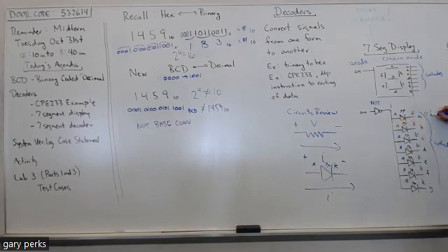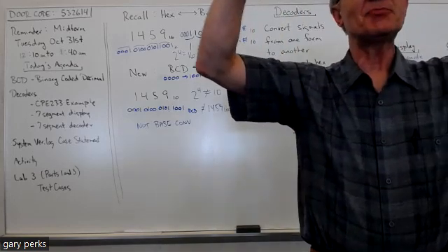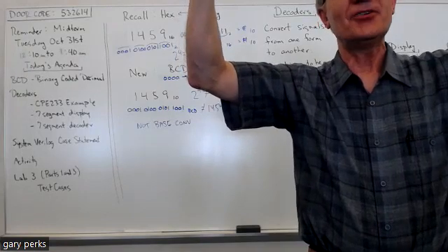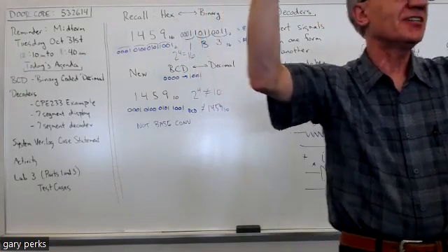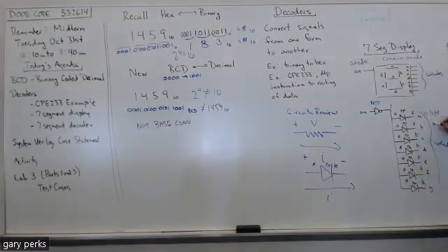So if you put a 0 on the cathode of the segment, that segment will light. If you put a 1, well, now you've got equal voltage on both sides, right? You'd have 5 volts on the anode and 5 volts on the cathode. And if you have equal voltage on each side of something, what's the voltage across it? 0. And is any current going to flow if there's no potential difference? No. So you see, that segment would be off. Okay, so with a common anode, a 0 is going to light the segment, and a 1 is not going to light the segment.